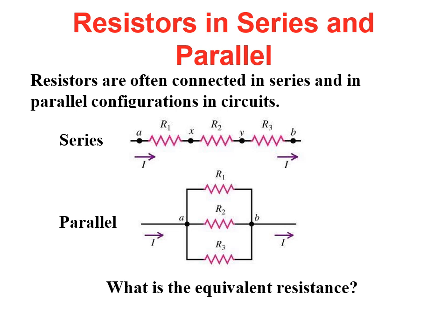Then we move on to parallel resistors. Now the two terminals of the resistor, the left and the right hand side, if they are joined together, then we say these resistors are in parallel. Here we have three resistors, R1, R2 and R3. All three resistors on the left hand side are joined together at point A. On the right hand side, they are all joined together at point B.